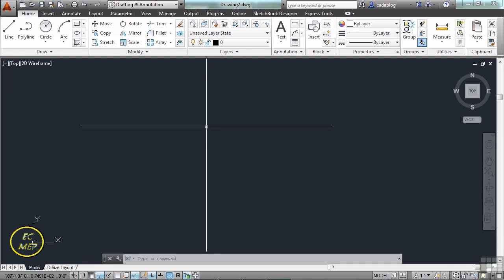You can draw a polyline, or p-line as they're often called, just using coordinates, relative coordinates, polar coordinates, length, just 2 points, etc. Lines can also be drawn as arcs. You can even switch from line to arc while you're drawing a polyline. And when you go to edit them, you can do the same thing. Polylines are very versatile and have many functions. In fact, I know several CAD drafters that don't use lines. They use p-lines because you can do things with them that you can't with a regular line.